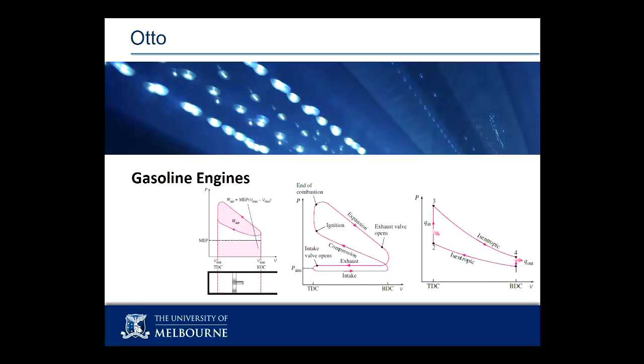You can have 2 strokes giving me my entire power cycle, which is say compress, bang, expand, work done, work released. Or I can have 4 strokes defining my power cycle, which is to say suck in my air, compress it, bang, exhaust it. So that's what's referred to as a 4-stroke cycle.